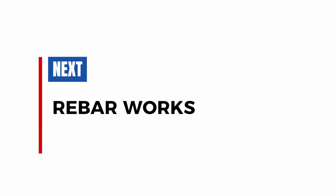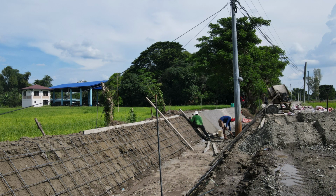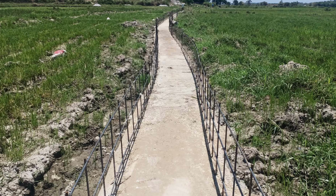Next, rebar works. In this stage, the reinforcement of foundations is being prepared according to the structural schedule along with its formworks. The proper and standard concrete cover should be observed during the procedure. Starter bars for columns and walls should also be installed accordingly before concrete pouring.